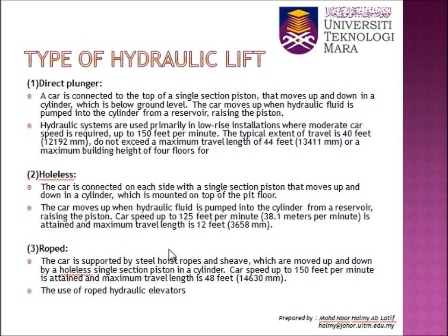The car is supported by steel hoist ropes and sheaves, which are moved up and down by a holeless single section piston in a cylinder. Car speed up to 150 feet per minute is attained, and maximum travel length is 48 feet.